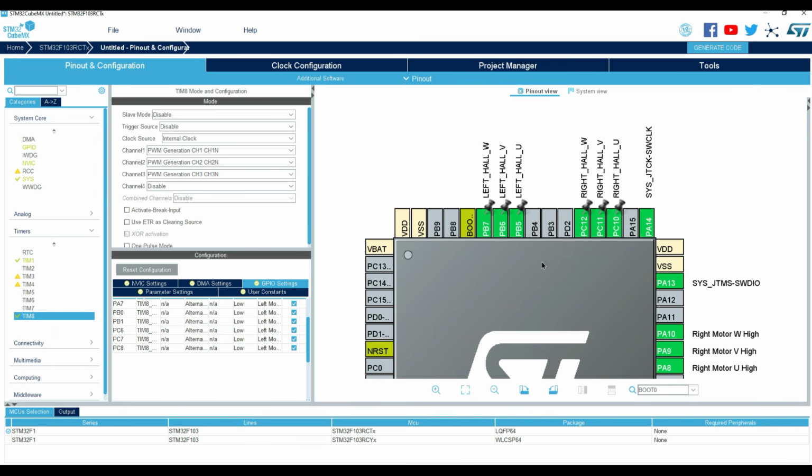Can we change these pins? Only if that pin has the same timer channel alternate function. So they are the correct alternate function pins. So finally, PWM timers make the motor turn. Hall timers tell PWM exactly when to turn. Both are required, it cannot work without either.